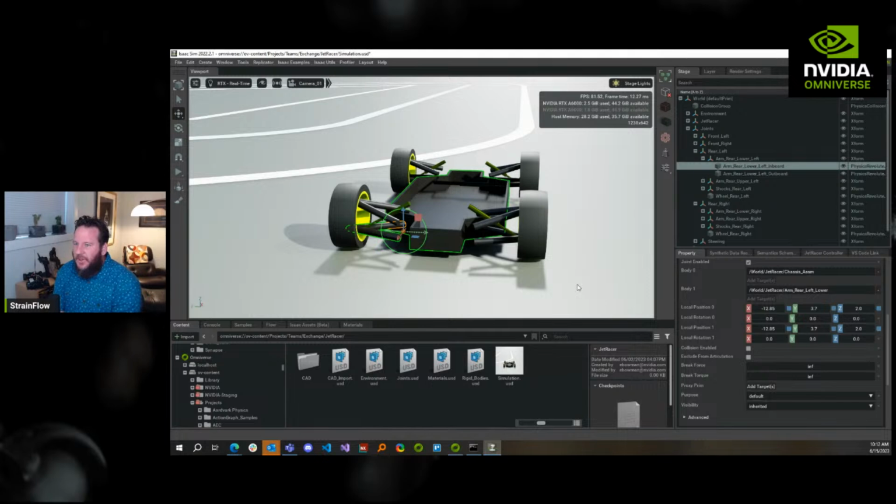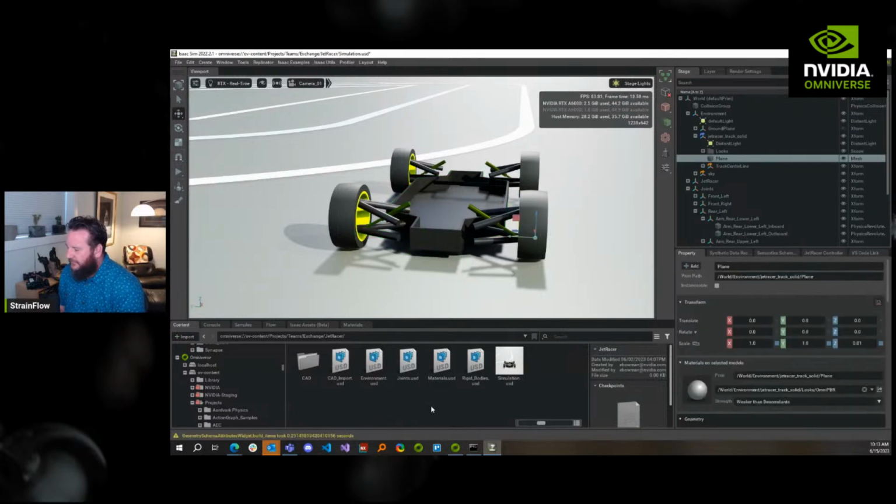So what works better is to have everything modeled from the global origin that you can, so that instead of giving it an assembly constraint, you just always have it at its zero location. You base it off that origin, but then you build axis systems and datum geometry where it belongs within the overall assembly. So you model it in these local coordinate systems, but really its origin is at the global origin. That's the way to go for large assemblies. It's just lighter weight that way. Anyway, we're doing that practice here in Onshape.